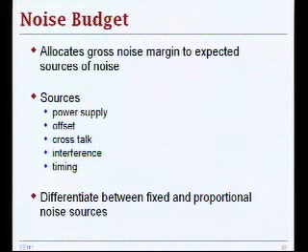And the sources can be various. You can have power supply noise, you can have offset. Basically, you can model your digital system with noise as a transmit-receive type of configuration, and you may have offsets in transmit and receive parameters. Then you can have crosstalk, where you can exhibit either inductive or capacitive effects.